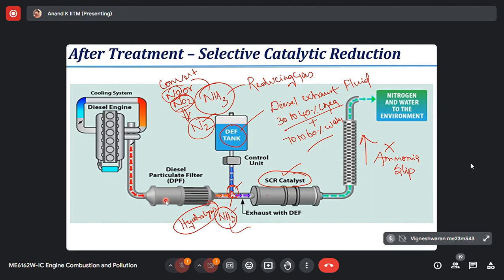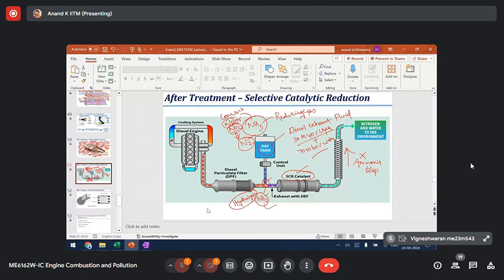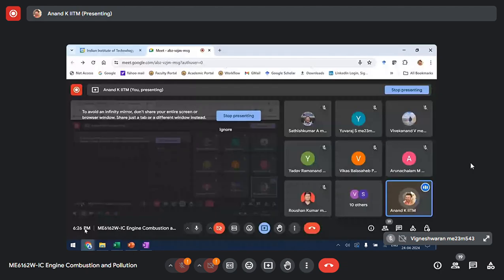You need more than one device for diesel engine after treatment control. So arranging these devices properly is also an important task that you need to look at. Like I have said, you have to have a reduction bed followed by an oxidation bed in a three-way catalytic converter. Similarly, here in a diesel engine after treatment system, you need to have the DPF located before the SCR. So these are important points to be noted from a practical implementation perspective.